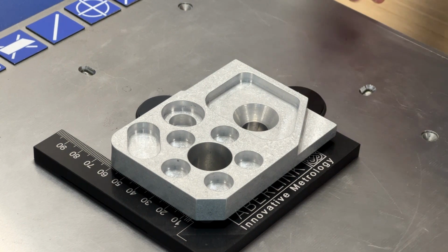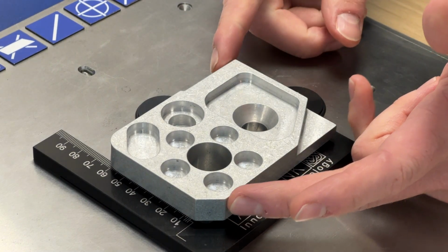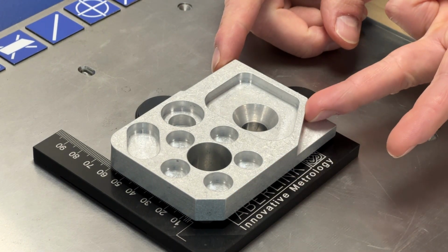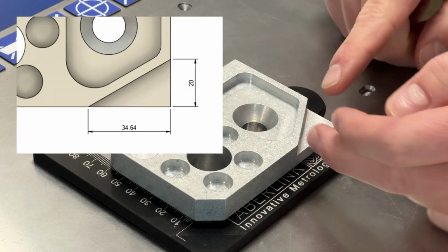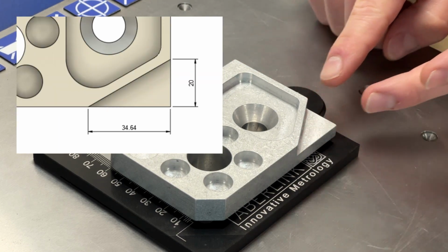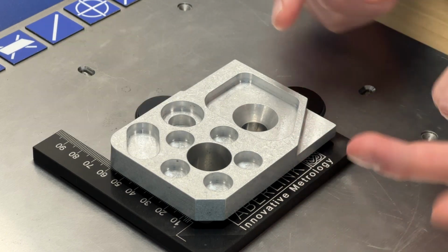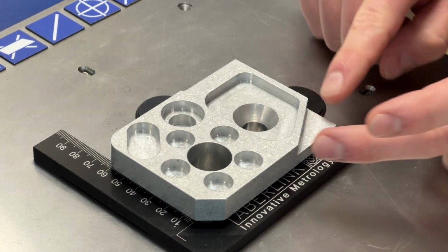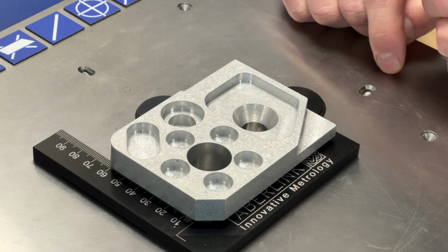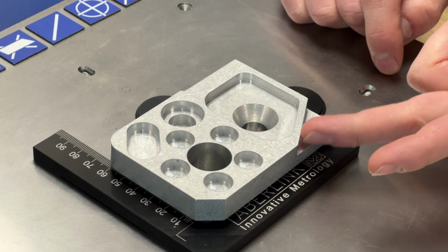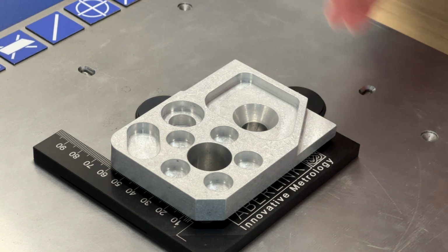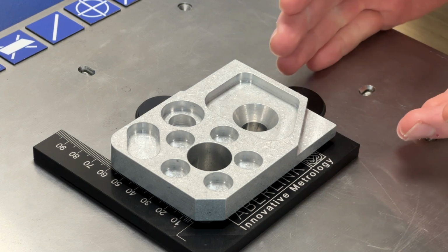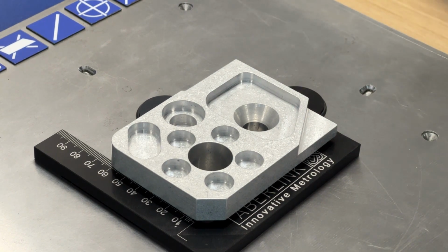The example that I'm going to cover on the test block here is we're going to measure this line, and this line. And what we're looking to do is work out essentially the shoulder height and depth, or width and depth if you want to call it, between these two. So whilst we can measure the lines, we can't actually measure the points. They are going to be constructed features that we have to use the software to create and then dimension. So let's get those measured.